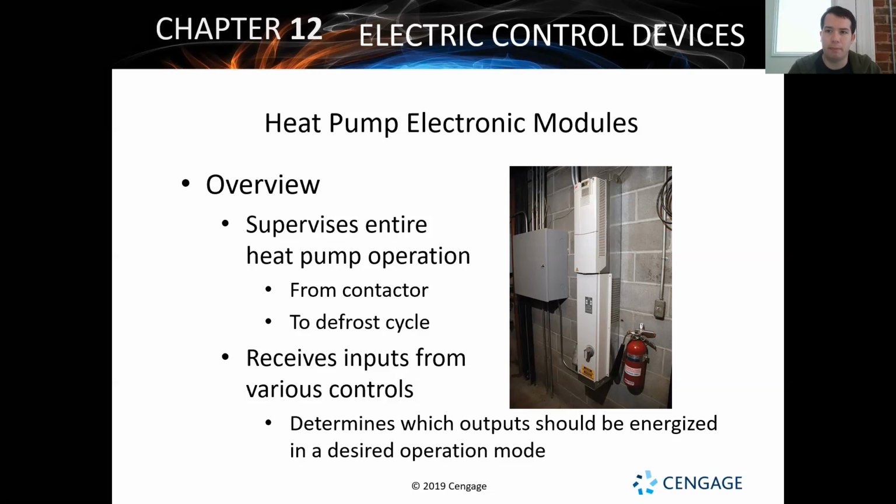but for a heat pump especially, because when a typical heat pump gets close to about 40 degrees and closer and closer to the freezing temperature of water, 32 degrees Fahrenheit, that's when we're going to see an outdoor unit start to build ice onto it. If you've ever gone out to your unit in the wintertime and seen ice on the outside of it, that is it frosting up. Now, if the system's failing, it can frost up because of a lack of refrigerant or a lack of airflow. So change your filters, make sure that your coils are clean, and make sure that your refrigerant is properly charged.